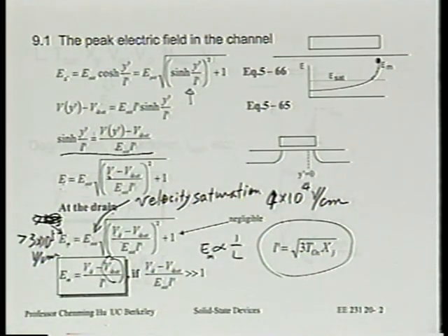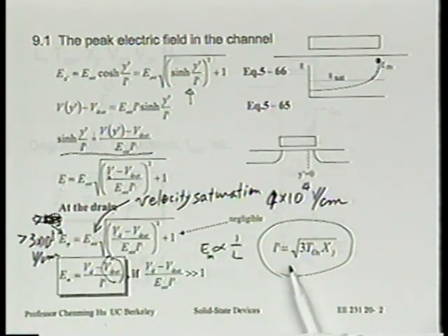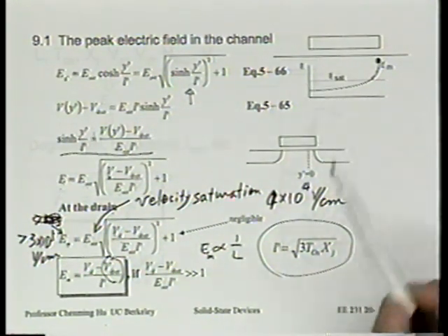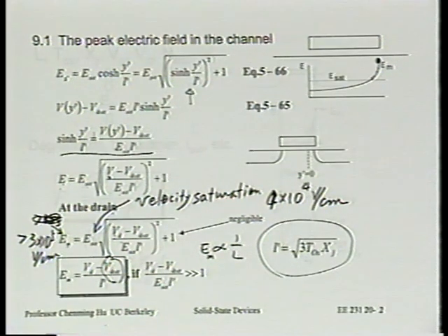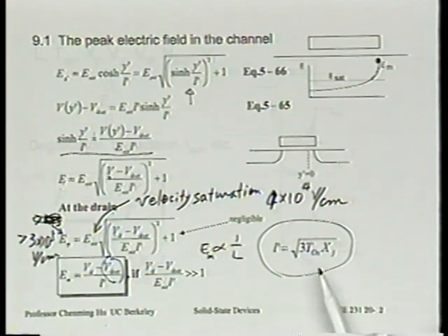Does that really mean that the doping concentration doesn't have any effect? It's not true either, because when we look at this quasi two-dimensional Poisson equation, the Gauss box, we always argue that where we draw that box is somewhat debatable. We drew the box at the junction depths, but we think maybe doping concentration or X effective could still have some impact. Maybe. But we just don't think it's as strong an effect as this.